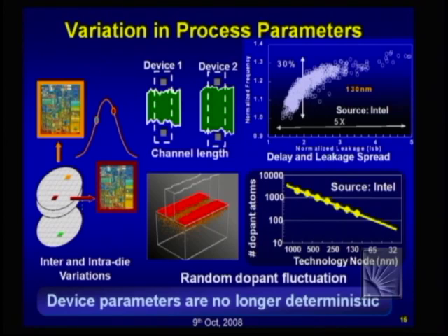The similar impact can be in analog circuits. So, these phenomena are significant in terms of logic and memory design, and for a set of Intel processors, they have seen that due to these variations in device parameters, we have a corresponding variation in system parameters, and this is the system leakage and system frequency for processors. You see that for the same process, same design, after manufacturing, we have 30% variation in frequency, and we have 5x variation in leakage current for 130 nanometer technology. If you go to 45 or 65 nanometer, this variation can be more than 100x.